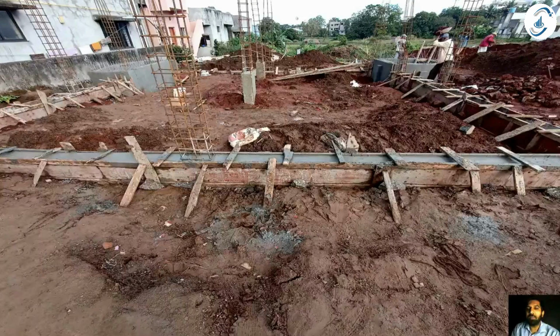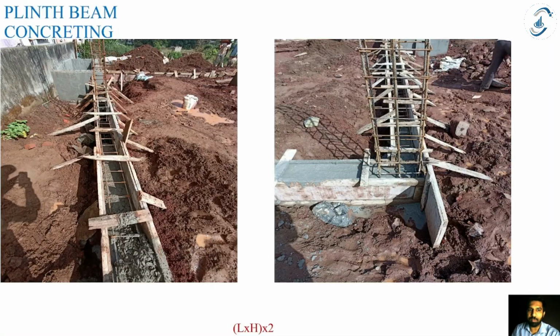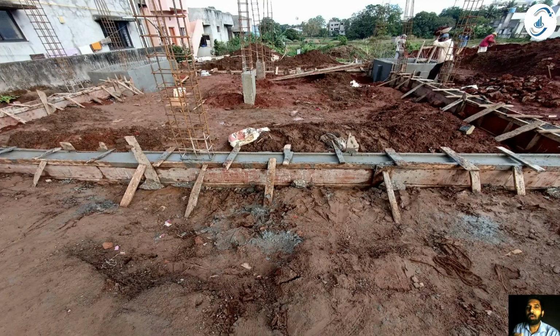After the plinth beam, we have columns again. So we already know how to read column drawings. What we have learned till now is how to read foundation drawings, pedestal column drawings, and plinth beam drawings. Above the plinth beam we have columns, and this process is the same as we read the drawings for pedestal columns.